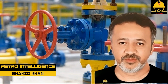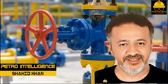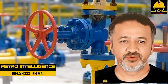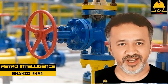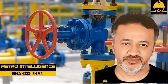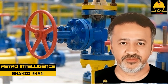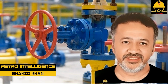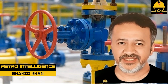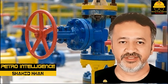Gate valves should not be used to throttle flow for extended periods. Turbulent flow rates across the valve body will cause metal erosion, seat damage, and damage to the flow control element, which can prevent the valve from blocking the flow completely. The seats in a gate valve fall into two categories, replaceable and fixed. Smaller valves typically have fixed or cast seats because it is easier and more cost-efficient to replace the valve than to replace the seats. In most cases, a gate valve has two vertical seating surfaces.